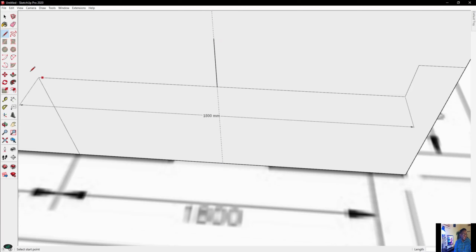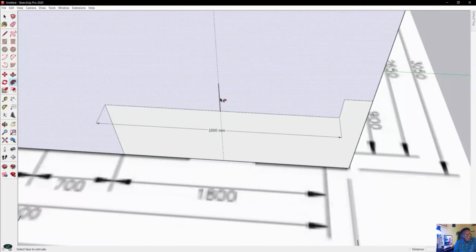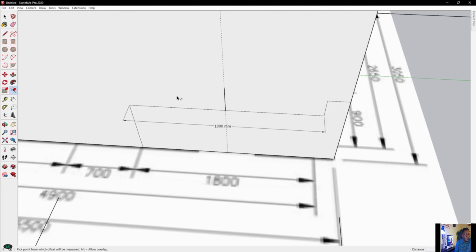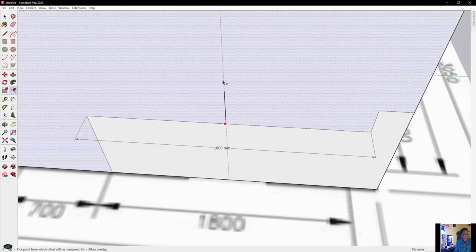that was the problem. This is not the offset tool. The offset tool is this tool here, not the one above. The one above is called a follow me tool, which is another advanced tool. Okay, so we're going to use the offset tool. All right, so I'm going to click that line here. And now the way the offset tool works is, if this was an element here, as you can see, if I click it, it's going to offset it to be a particular distance here.